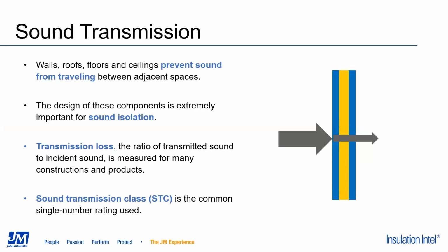So I want to point out that STC ratings are only valid for an assembly, not an individual product. STC ratings aren't like R values. They can't be added together. Sound passing through a wall is a much more dynamic process in comparison to heat. So just want to keep in mind that no piece of insulation has a certain STC value. Even if you measure it and get it tested just individually by itself, that value has no meaning once you stick it into a wall. That number only applies if that's the only thing separating two spaces.